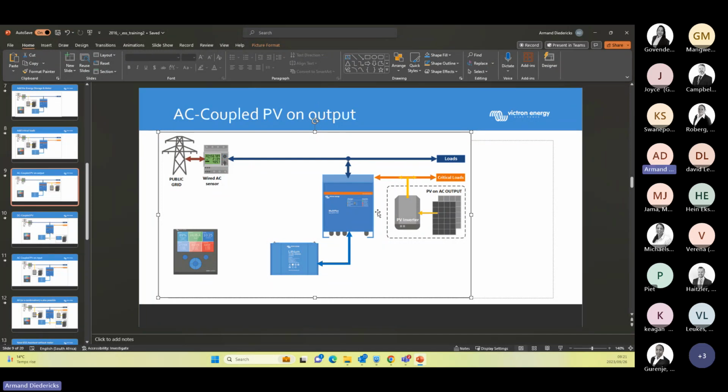Ideally, with the Multiplus or the Quattros, there's AC output 2, which means when your PV modules produce so much power that it charges the batteries and takes over the load, and there's excess power, it can go back to the non-critical load if you have geysers or aircon or whatever the case may be. So that's an advantage. But yeah, AC coupled is ideal.